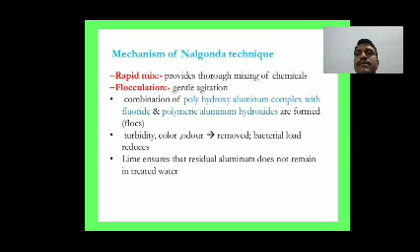In this stage, formation of floc from destabilized colloidal size particles occurs. It is achieved by gentle and prolonged mixing for a period of 10 to 15 minutes with a speed of 2 to 4 rotations per minute.